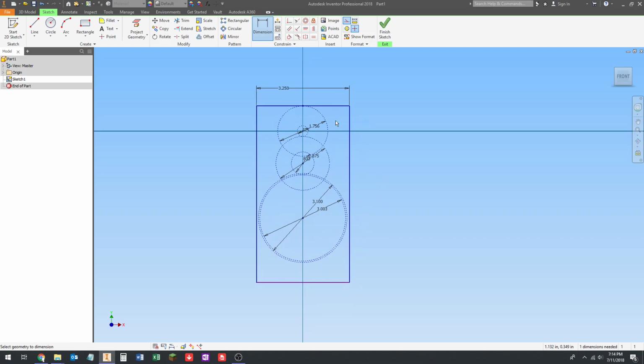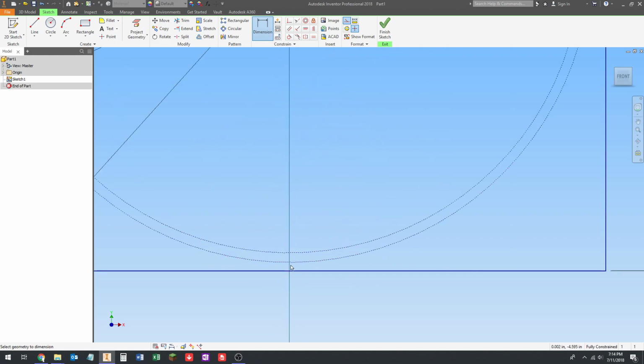And then we're going to do the side. We're going to do the same thing. Click on the line with the dimension tool active. Then we're going to place the dimension down somewhere readable. We're going to go, I think, 5.5. Yeah. Okay, so once again, we just want a little space.